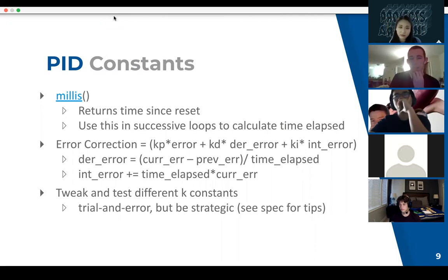As you can imagine, you might have a standard distance you want your sensor away from something. However far away you are from that distance will be your error, right? So that's a pretty simple measurement to take. You just see how far you are, and you subtract off where you want to be. That's your error in distance. But the derivative and integral of the error might be trickier to do.